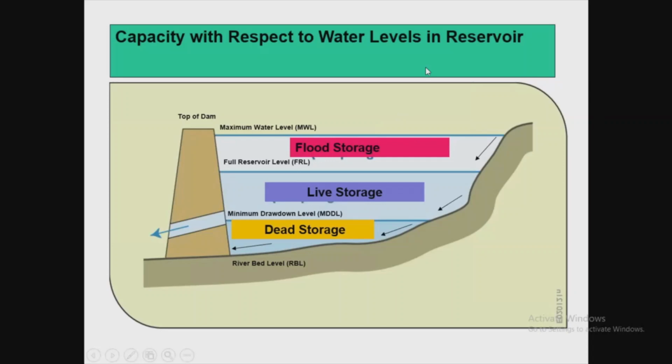Whenever it drops sediment, it is deposited here. So whenever it is depositing somewhere here, our live storage is encroached, we can say. Now, suppose I have taken X million meter cube of live storage of water. Out of that, if it is encroached by 20%, then X minus 20% water is now available after 5 years or after 10 years or after 11 years.